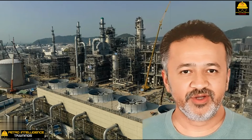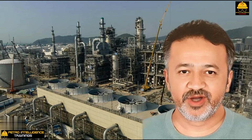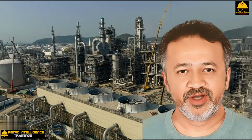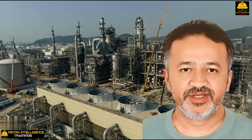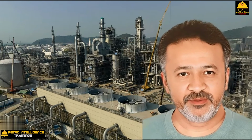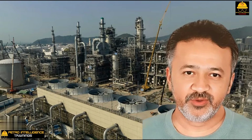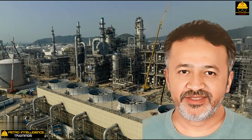To restore cooling, you might wish to try the Norm Lieberman method, which consists of reversing the polarity of the three-phase fan motor electric leads. The fan will now spin backward. Depending on the nature of the deposits, a portion of the accumulated dirt will be blown off the tubes, but all over the unit. Personnel should observe this procedure from a safe distance.